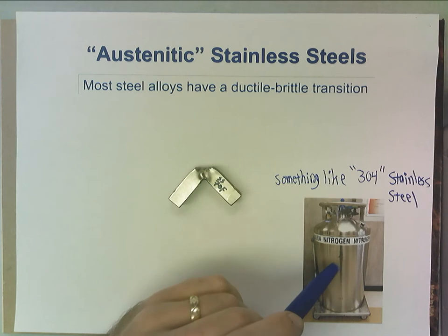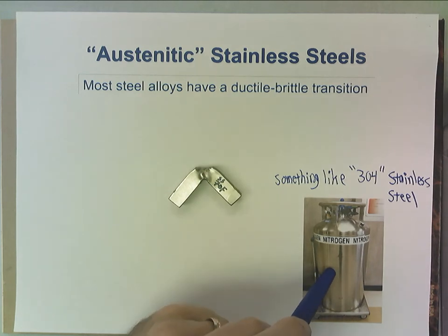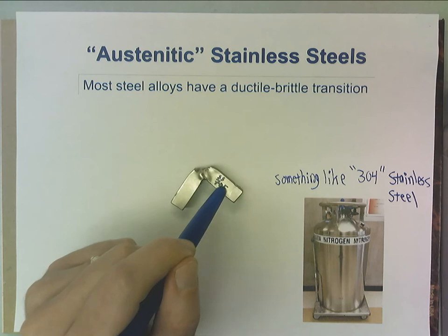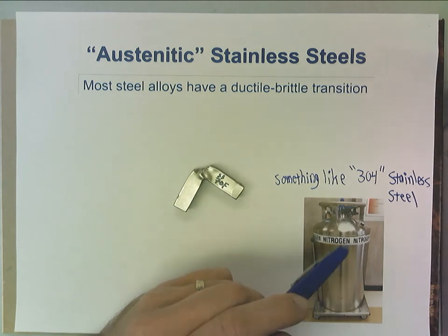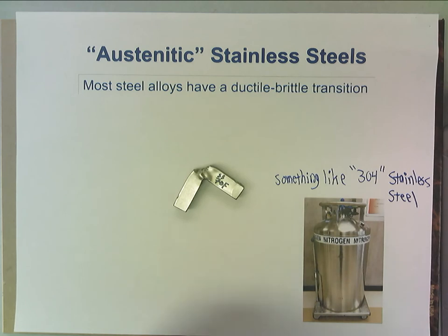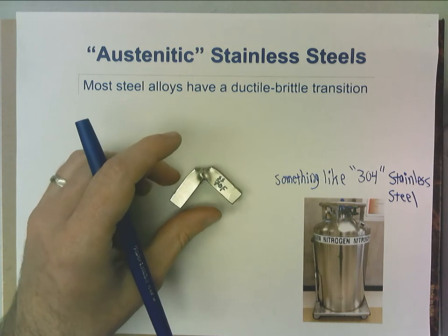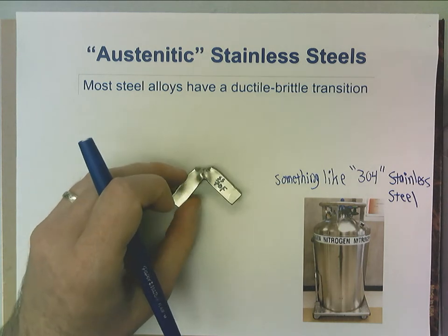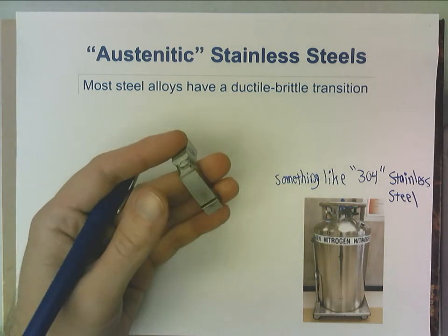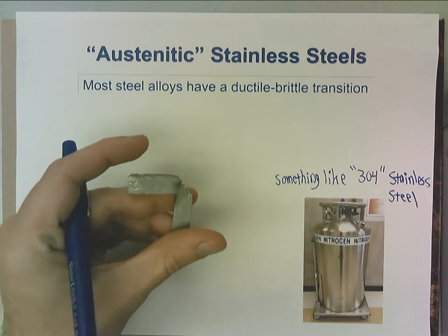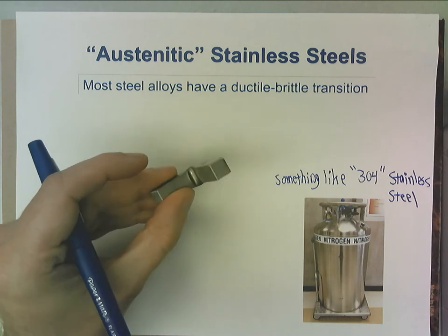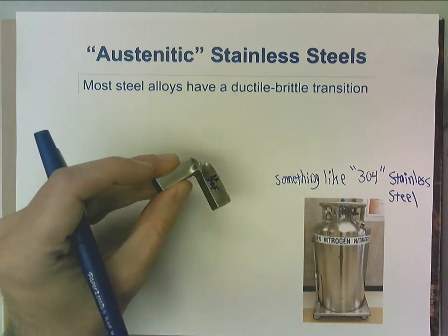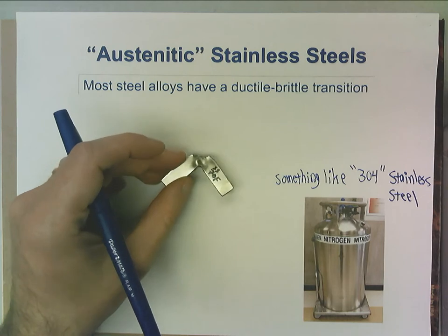That means by making this out of a high alloy stainless steel, like this material, if I accidentally bump a wrench into this, it doesn't shatter down the side and release liquid nitrogen all over me. I would prefer that as opposed to being covered in liquid nitrogen. So, this material is what we're going to make that out of. Very, very tough, very, very ductile, but also with fairly reasonable high tensile strength.